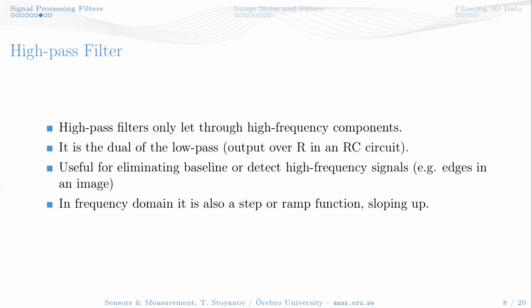Now, why do I talk about sloping here? A ramp function. What I showed you there was not a ramp function, right? This was a step function. It's because this is the ideal version of the filter, right? If we implemented that filter in reality on a real RC circuit, then the real representation would not be a sharp step. It's going to be kind of a sloping ramp.